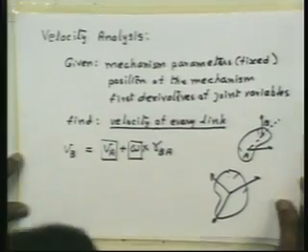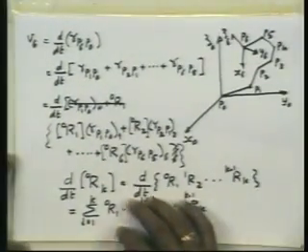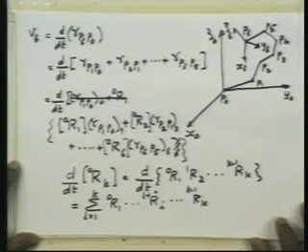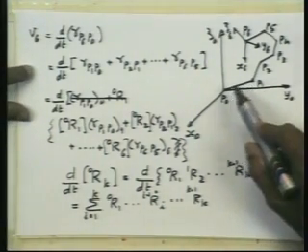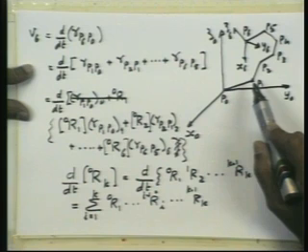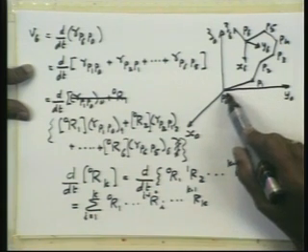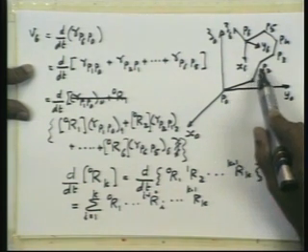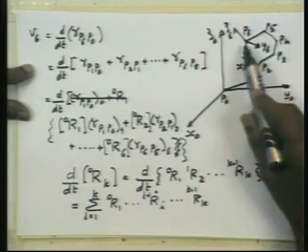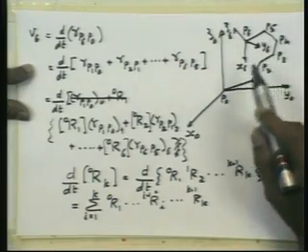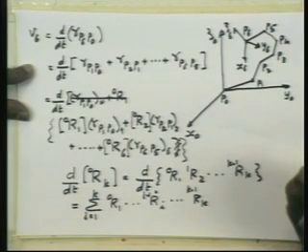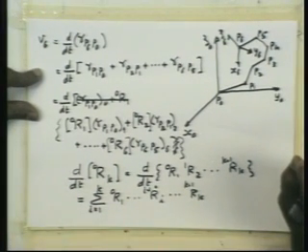Now we started doing this calculation, and that is done in the traditional way. The manipulator is represented by these segments P0, P1, P1, P2, P2, P3 up to P5, P6, where P0, P1, P2, P3 etc. are the origins of the reference frames we fixed on the links.